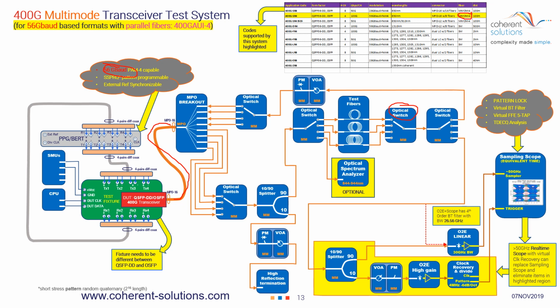The main difference between these faster 400 gig signals and the 100 gig is that most of them use the PAM4 kind of protocol here. Again, remember the PAM4 is 4 different levels, which carries 2 bits. So for each clock symbol, we are carrying 2 bits times the clock rate that is available. So in this case, since we are running at 56 gigabaud with 2 bits, each one is carrying 100 gig, and there are 4 lanes. 4 times 100 gives us the 400.